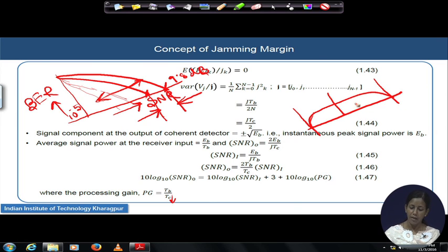Whenever I try to have a higher spread, the original bandwidth that we are trying to utilize will shrink. So, the lower the value of TC you start with, the more the bandwidth will be, there is no doubt about it, but the actual signal bandwidth that you really get will keep on shrinking.